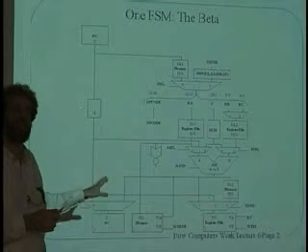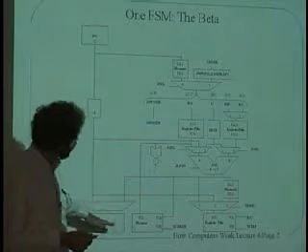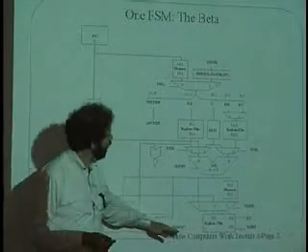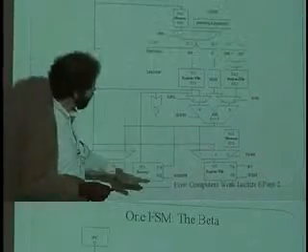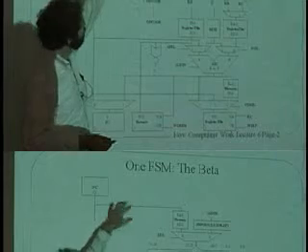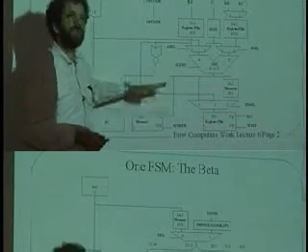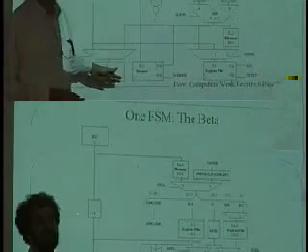Architecturally, it's still a finite state machine. It still has a structure where there's memory over here, and then there's nothing really more than logic up here to say, if I'm in a certain state, then go through a bunch of logic to determine what the next state is going to be, and then when the clock goes off, make the current state that next state, and change it to the current situation.